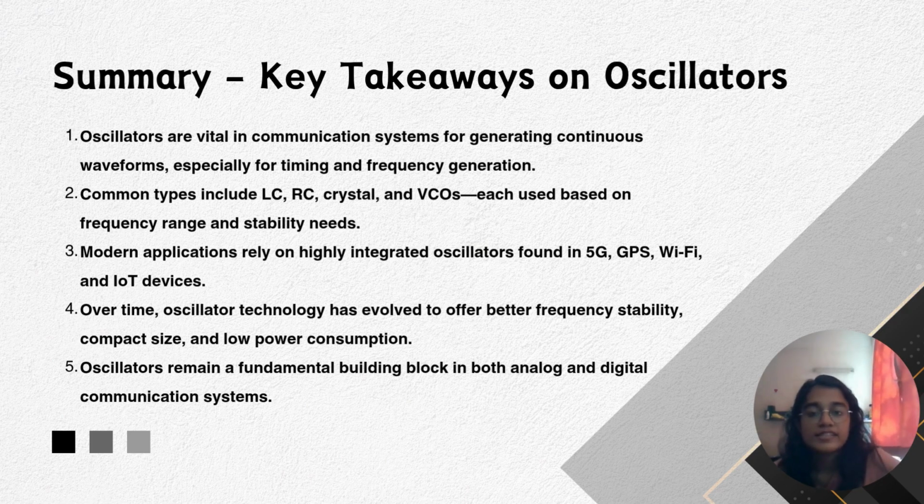Finally, let's take a look at the key takeaways on oscillators. Oscillators are vital in communication systems for generating continuous waveforms, especially for timing and frequency generation. Common types include LC, RC, crystal, and VCO oscillators, each used based on frequency ranges and stability needs. Modern applications rely on highly integrated oscillators found in 5G, GPS, Wi-Fi, and IoT devices. Over time, oscillator technology has evolved to offer better frequency stability, compact size, and lower power consumption. Oscillators remain a fundamental building block in both analog and digital communication systems.